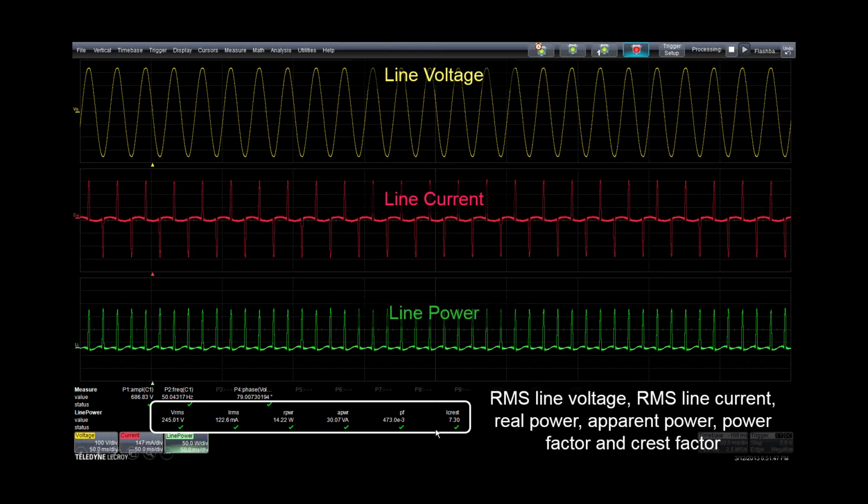So this is really not ideal, to have a power factor that's this low. This can cause a number of problems. Basically, you have to design the input of the power supply to handle a current load which actually can't be used by the power supply itself. So you have to over-design the input to the supply.